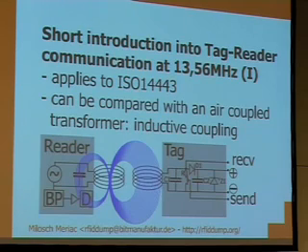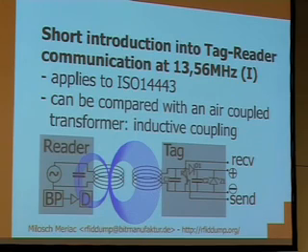And the carrier is received by the tag by using a transformer approach. It's similar to transformers. You have two coils, and it's very much the same as transformers. You don't have the coil that connects it, but you have an open magnetic field. So the tag receives the field. You see C1 connected on the tag, and it makes sure that we are resonating to the field, so you can make sure that you have the highest possible output.